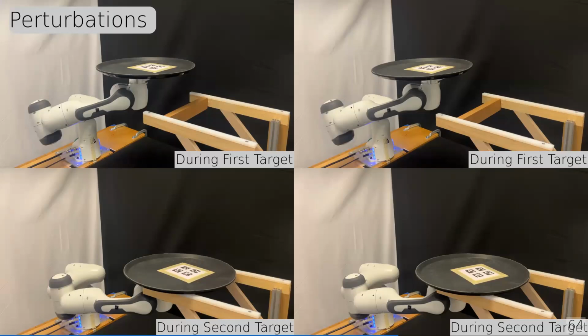I want to clarify that the inputs to the MPC are not just the state of the tray, but also the state of the robot. If it was only the state of the tray, we wouldn't even need faster than 10 hertz, because our measurements would be stale anyway. But if you were to perturb the end effector, it'd actually be easier, because we have state feedback at a kilohertz and we're directly controlling the end effector. We can just react. Perturbations on the tray are much harder because of the delay, but also you can't directly control the state of the tray with your motors. You have to do it through friction.